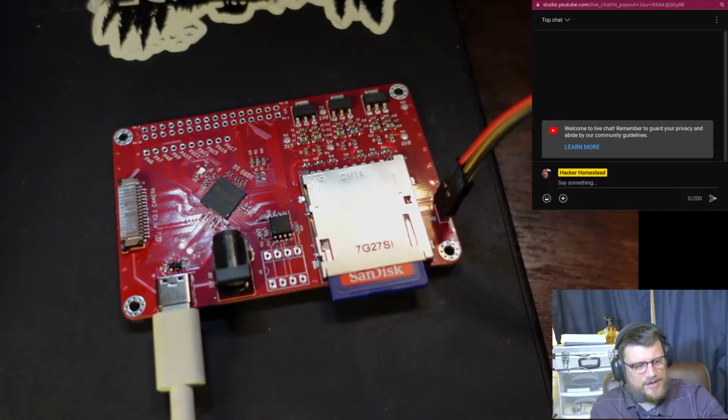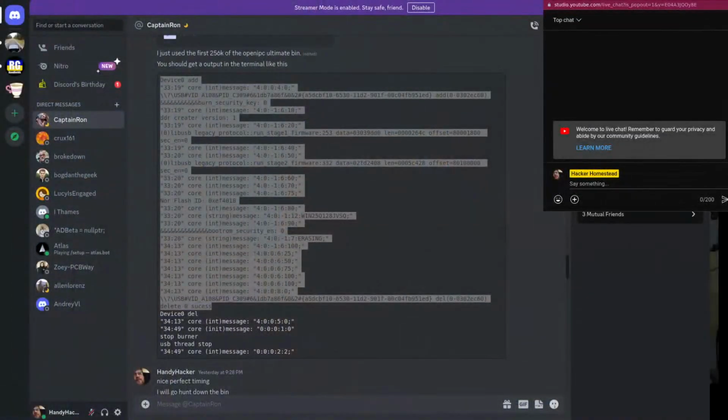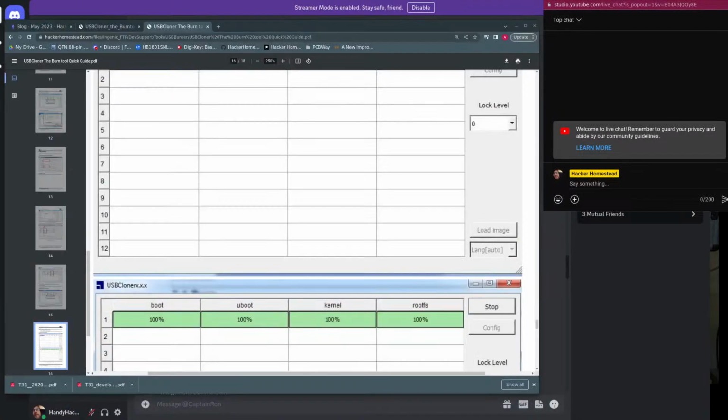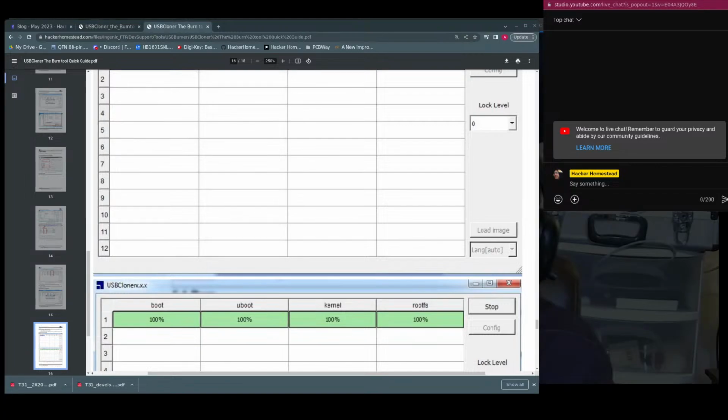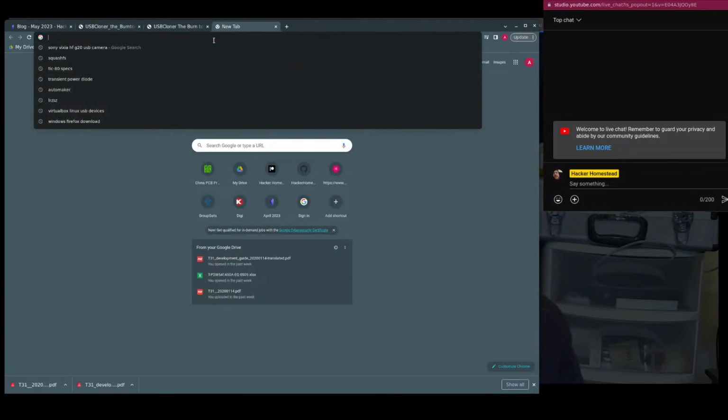So on the story here, I was able to flash U-boot. Now, I need to make sure I document where that came from. Did I make that myself? No. We're still cheating a little bit. We need to get U-boot compiled. Been doing just fine getting Linux compiled. Need to move on to the final frontier of getting U-boot compiled. But right now we're stealing from OpenIPC's wonderful work.